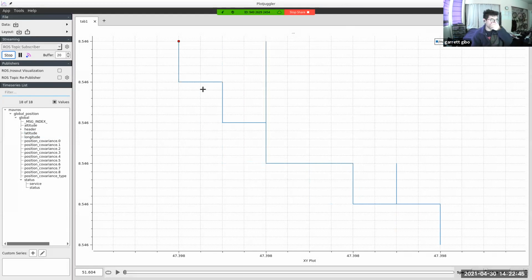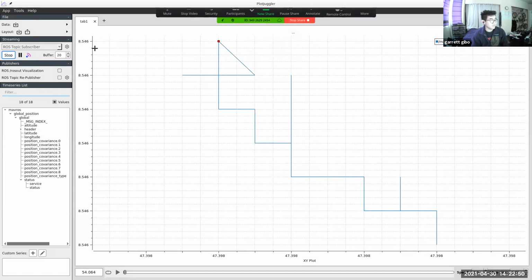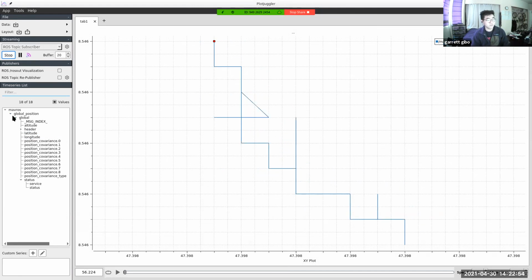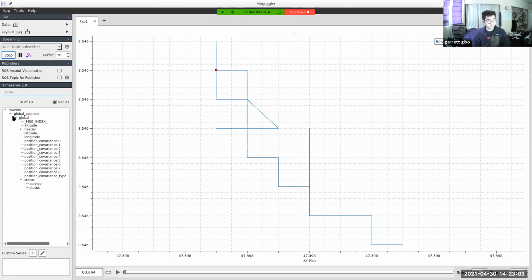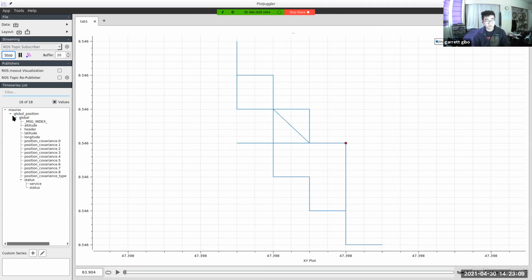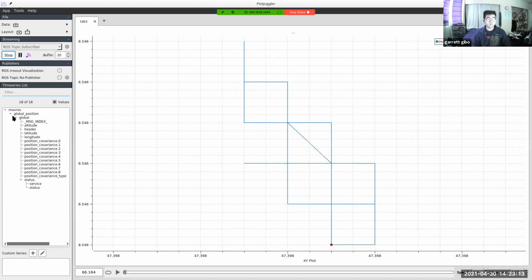Position in this instance isn't super useful. This is really just noise right now. If you look at these axes, these numbers are all the same. Where this is more useful is when you're designing your controllers and trying to tune the vehicle. We've already added some parameters related to the orientation of the vehicle, the roll, pitch, yaw, the linear actuators, what is actually being applied to them, what the target values are, and what the current values are.